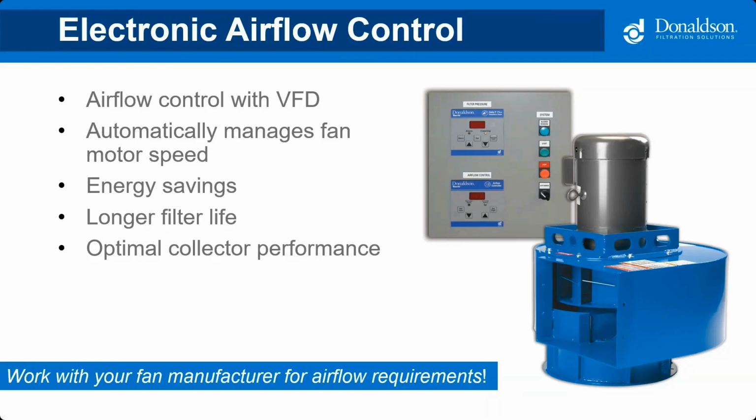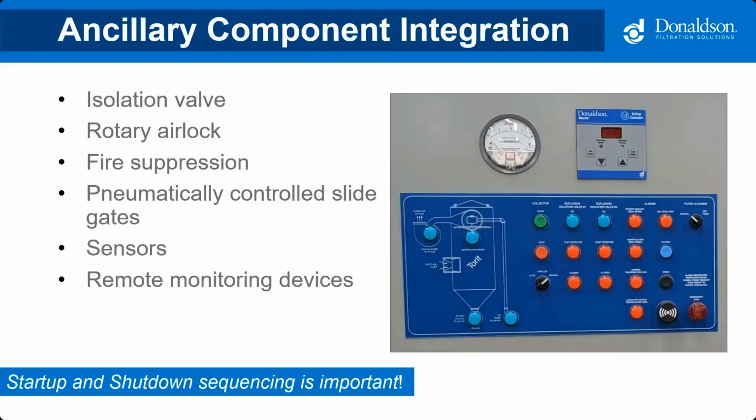And just as a heads up, it's important to work with your fan manufacturer to understand the airflow requirements. Often they will recommend oversizing the fan slightly to allow for the maximum benefits of a VFD if you were to use that in your system.